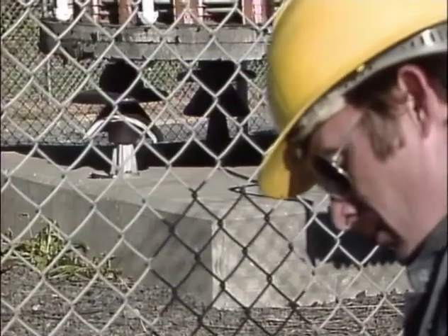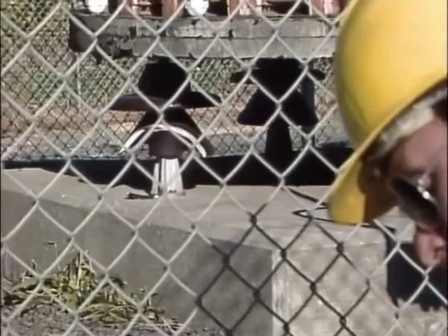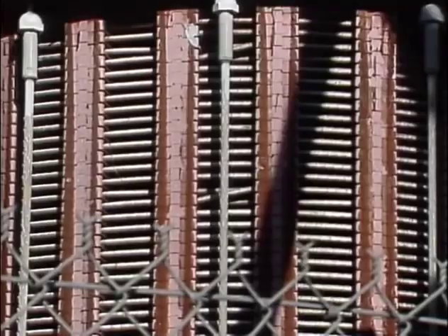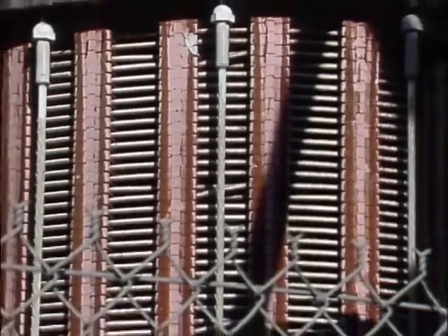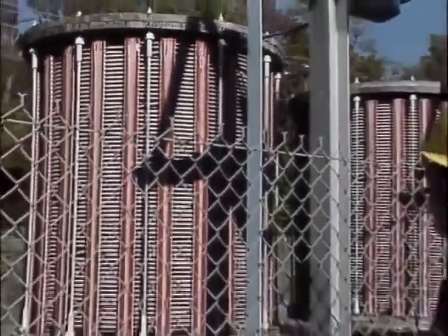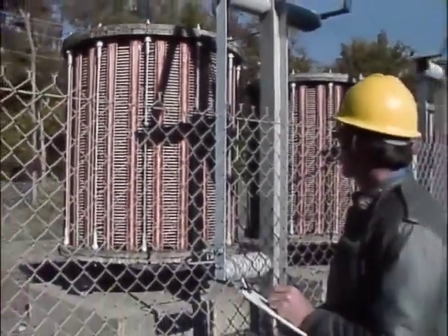The support insulators are checked for breaks, cracks, or chips that may weaken their support of the reactor and allow current to leak to ground. The winding shims are also checked for cracks or chips that may allow current to arc across windings. Sometimes current leakage or arcing is indicated by buzzing noises at the reactor, even if it isn't visible.